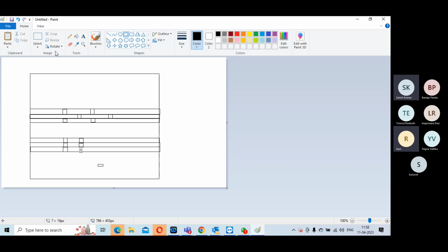In the past, we have used gate array cells. It is also called a spare cell? No, spare cells are different. Don't mix spare cells and this one. These are ECO-able filler cells. You understand that? The ECO-able filler cell is a fill cell, but you should not add an ECO-able filler cell for every fill. That's not a recommended thing.